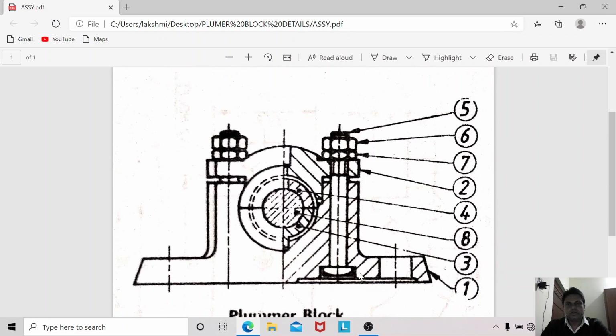Okay, I will show you the assembly drawing of this, where this is a half sectional front view, and you can see the individual parts being called, represented by these balloon callouts. We have already created these, and you just see there is a body and a cap. The bottom bearing and top bearing are compressed by cap and body, and these are bolted here and locked with nut arrangement. This is a simple arrangement.